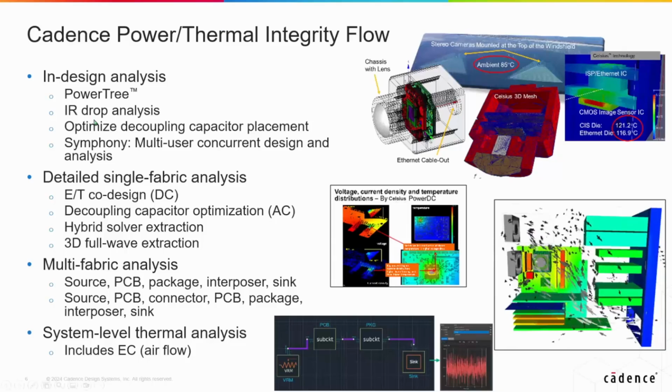Ultimately, we want to help you run IR drop analysis as you're actually creating the actual package, and help you make decisions on decoupling capacitor placement. Make sure you're placing those capacitors close enough so that they're useful. And again, we encourage the multi-user environment, both designer and analysis expert, being able to look at the same design concurrently and be able to make those changes. All of this ultimately helps to reduce the design cycle.